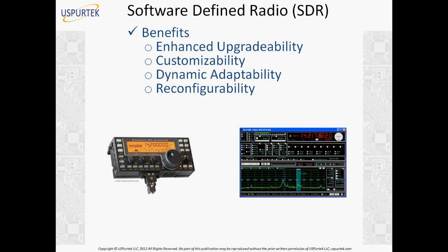So why do we need to reconfigure? What is the benefit of reconfiguration? We can implement new standards or protocols, like we have a new version of LTE, and now we have LTE Advanced, or Release 11 or Release 12 coming in. It's very easy to implement those new standards or protocols when you have a software-defined radio.